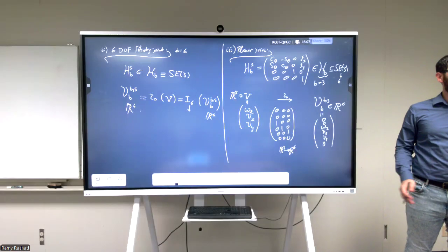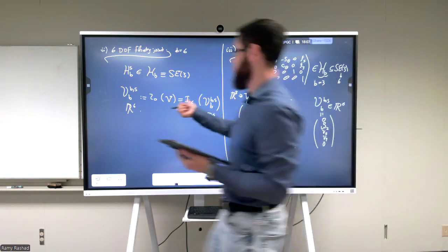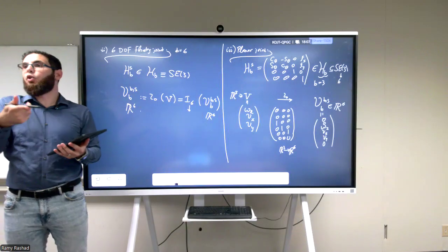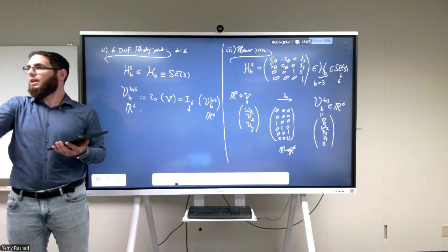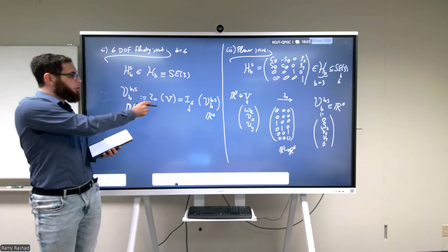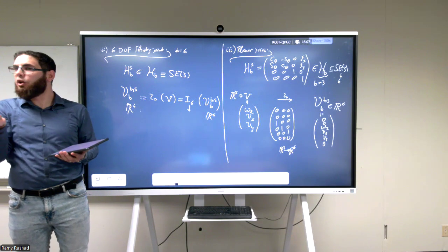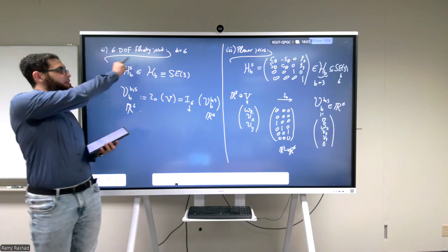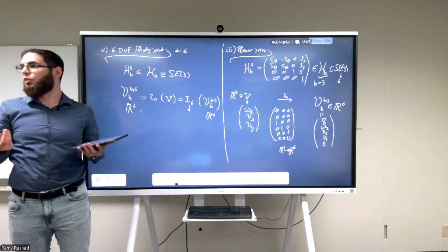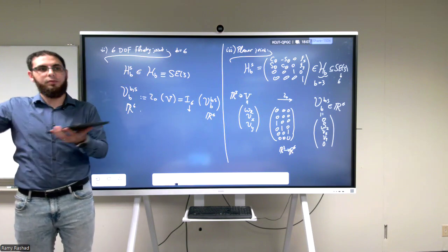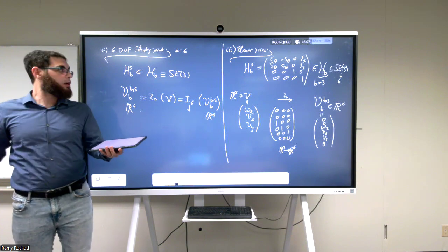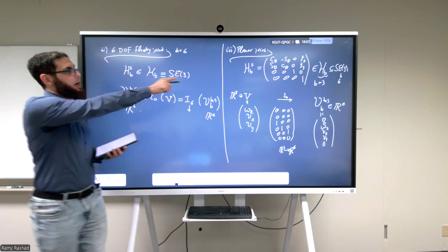Clear? So we're going to be dealing a lot with this generalized velocity of the base. Iota is the map that will transform this generalized velocity into a twist. And we're still dealing with homogeneous transformations to describe the relative transformation between the base and the stationary frame. They're given by this expression.